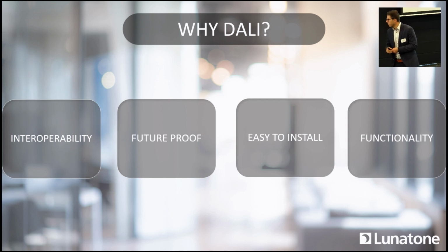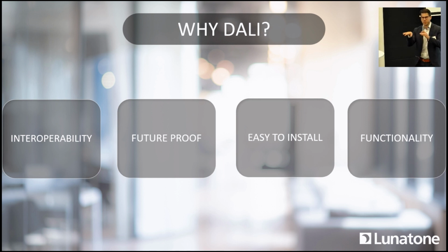It's future-proof, because as you have seen, on an existing installation you can now, with DALI-2, extend the installation very easily. You can add another bus DALI power supply with multiple application controllers. You don't have to worry about a single master controller and whether it can get implemented, if it's compatible.